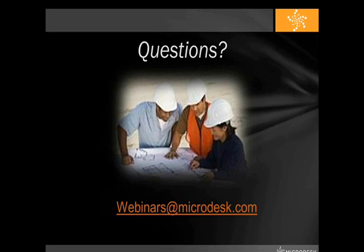Oh, that's a very good question, Megan. The way that Revit and Autodesk have designed this is to use the same engine from Robot Structural Analysis. When you send it over through the cloud, it's using basically what it would use for Robot Structural Analysis. That's why it's very useful to integrate with Robot Structure when you're doing the cloud analysis, because it can communicate very closely and very well.